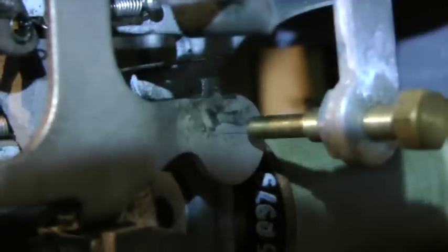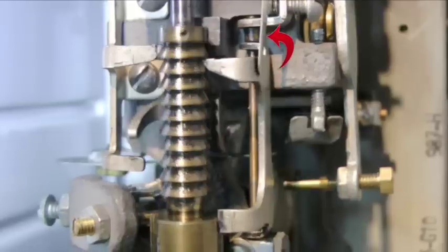For clarity, I have added a clip here using my spare parts switch, showing the mechanical motions of the vertical pawl. It is the tip of the pawl that engages the ratchet teeth. When the vertical armature operates, the release link is pulled free from the double dog tooth. This allows the tension of the double dog spring to force the double dog legs to engage the ratchets.